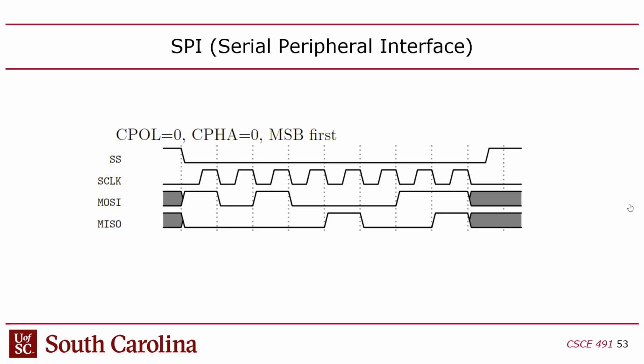I want the data to be stable for as long as possible before and after I read the data. Why? Because of setup and hold time. You guys remember setup and hold time from 611? Setup and hold time says that you have to have a stable input prior to the clock edge, right? That's the setup time.